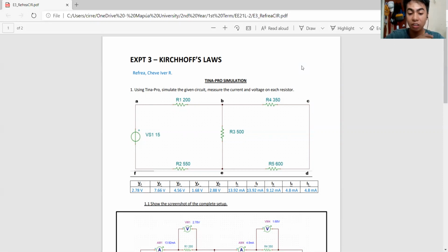Gustav Kirchhoff's current law is one of the fundamental laws used for circuit analysis. His current law states that for a parallel path, the total current entering a circuit's junction is exactly equal to the current leaving the same junction. This is because it has no other place to go, as no charge is lost. In other words, the algebraic sum of all the currents entering and leaving a junction must be equal to zero. The summation of in equals the summation of out. This idea by Kirchhoff is commonly known as the conservation of charge, as the current is conserved around the junction with no loss of current. So that talks about the KCL.